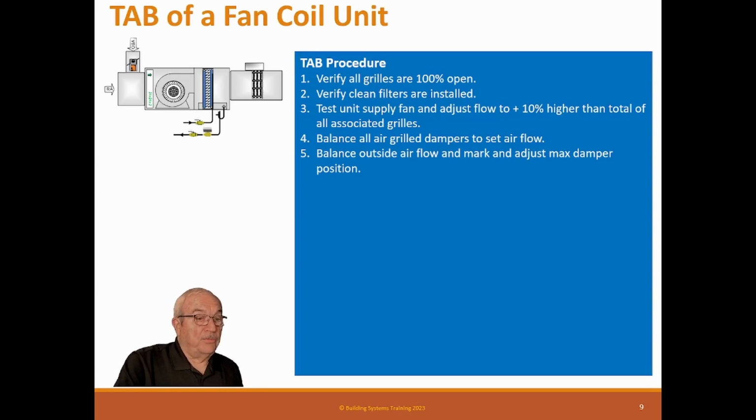At least 0.015. Yeah, but 0 is acceptable, but minus is not. So if you have negative air, you have to increase this. And the reason for that is some engineers don't calculate building leakage, and buildings leak just like ducts leak. If they didn't account for that, then you're going to have a negative building. So you need to do that.